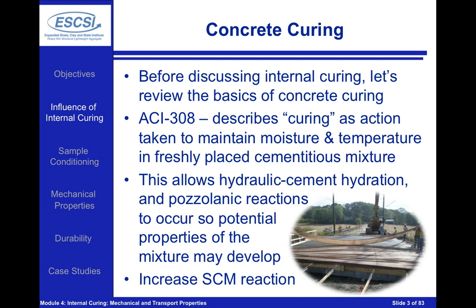By maintaining the moisture in a cementitious material, we're going to increase the amount of reaction that's taking place, the amount of hydration that's taking place, specifically the hydraulic reaction that occurs with Portland cement, and the pozzolanic reaction that will occur with supplementary materials like fly ash, slag, and silica fume. So the whole idea is by using internal curing, we're doing what we know is a good practice for concrete.